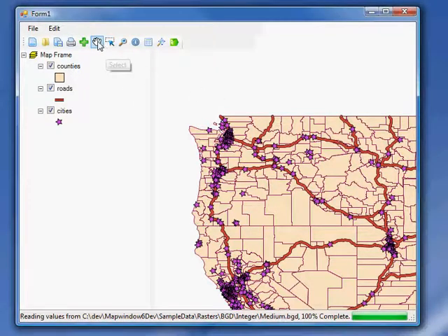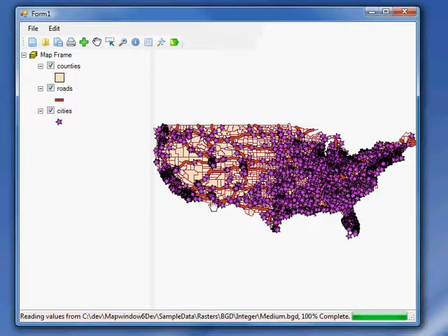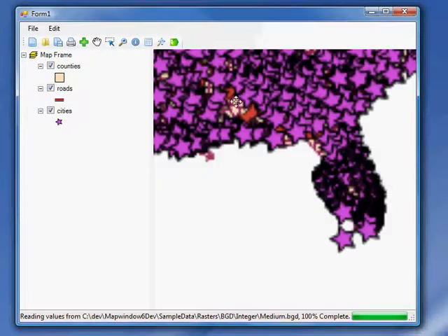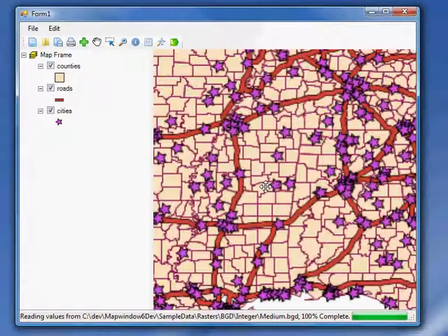The buttons up here that are important: you can use the Zoom to Max Extents button to reset the view to the farthest extent for the project. And this is your pan option and a zoom button, but because you can zoom with the mouse wheel, I tend to use the pan option and then just use the mouse wheel to zoom in.